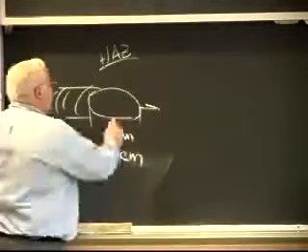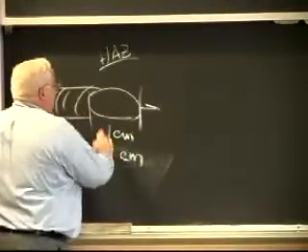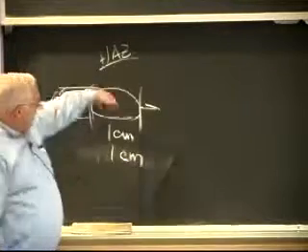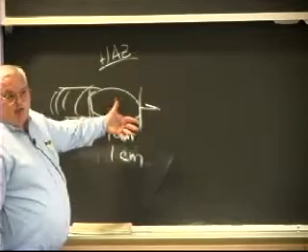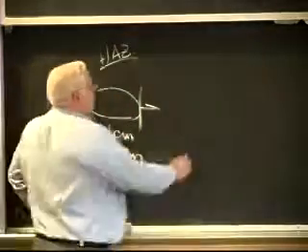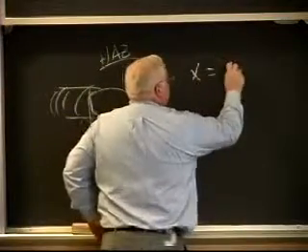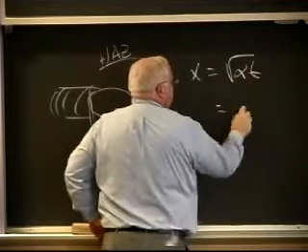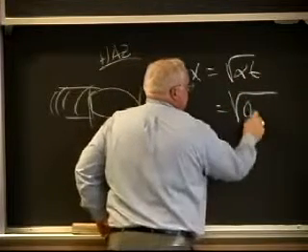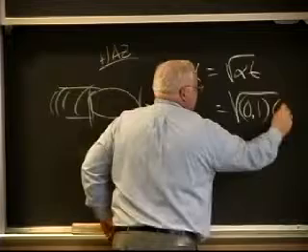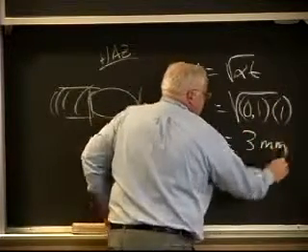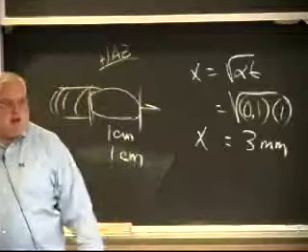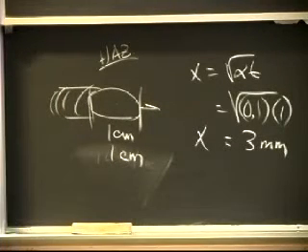So it turns out the time from the front to the back of the weld pool, where I have a heat source that's pumping heat into my base material, is 1 second. So X is square root of alpha T, and T is 1 second. If I'm talking steel, that means X is on the order of 3 millimeters. It's 0.31 centimeters, or 3.1 millimeters, square root of the 10th.